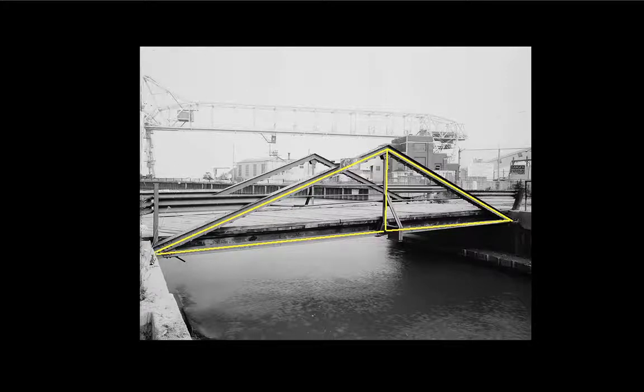But the idea is we'll assume that on one side of the bridge, in this case over here, we have a support that basically connects to the truss members, but it's a rotational support. It allows them to rotate in these directions. Now, again, this is not real life, but this is necessary to make the analysis easy.